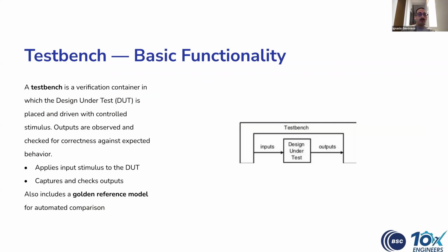So how do we proceed into verifying a design from lower levels to upper levels? Here is where test benches are built. So what is a test bench? It's a custom test harness for our DUT, or design under test, where we apply stimulus to that design and check the outputs of the design. Ideally, these checks are done against a reference model or at least in an automated way.